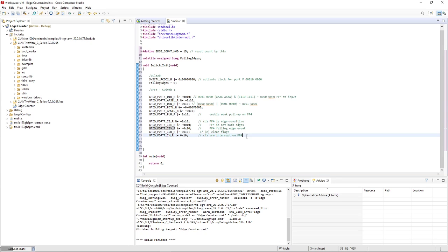There are a lot of pins on the ports, and right now we don't want PF3 or PF1 randomly triggering interrupts, well, we do want PF4, especially considering those are always going to be outputs since they're LEDs on the board themselves. So we don't want them doing random things.